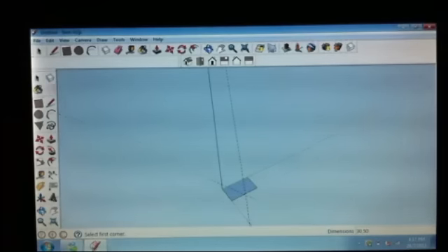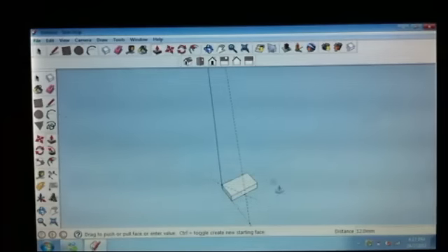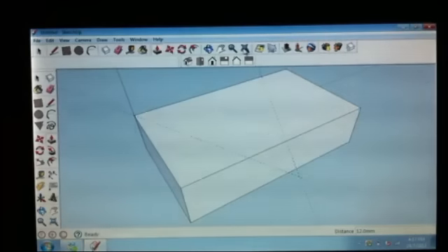And the thickness of the wood is always 12 in this case, so I'm going to key in 12, enter. So the leaf is here. Now this doesn't look like a leaf, right? So let's zoom extend again, and then get the leaf done. Now you can use curve arc here. And you bring the arc to the edge here.